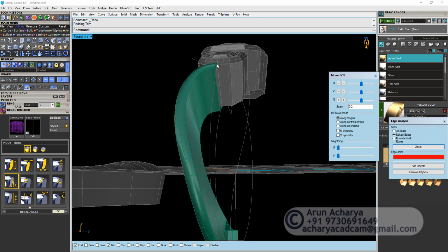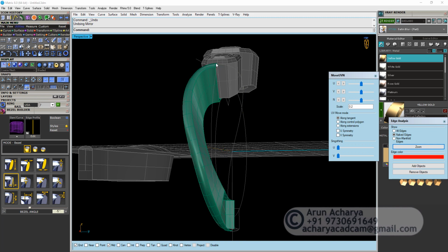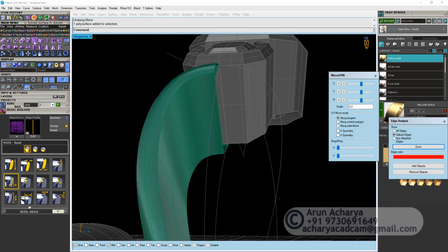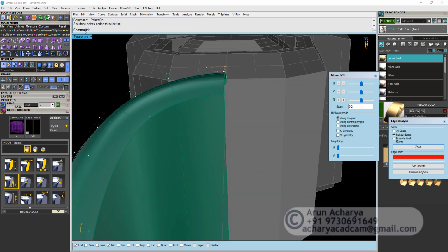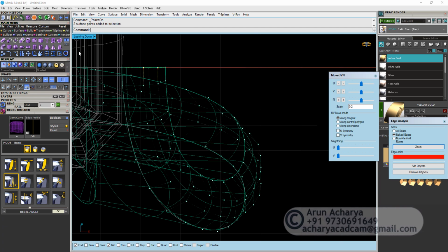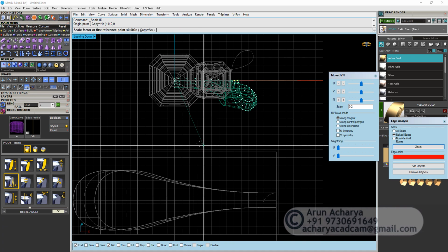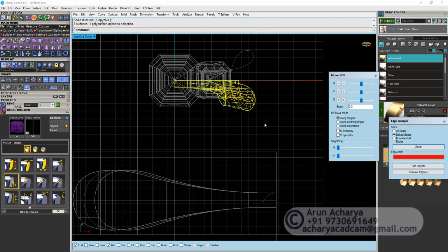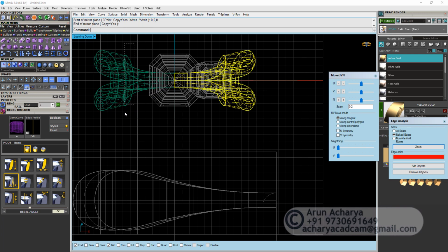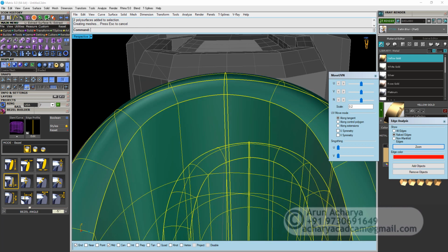okay, let's keep everything the same, but over here let's just extract this surface again, get the points and fix it with the same technique I use, which is Scale1D, F4. That's my center, and press enter because I already have like 0.3000. So right click and make sure the ortho is on and enter, press enter, join it, and now we're not gonna have this issue. Okay, so let's join this.